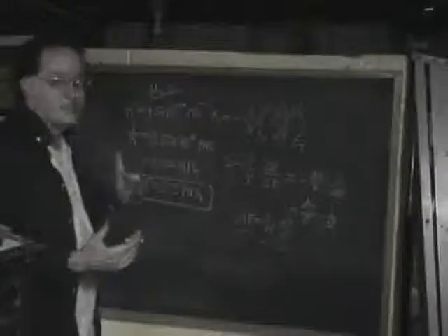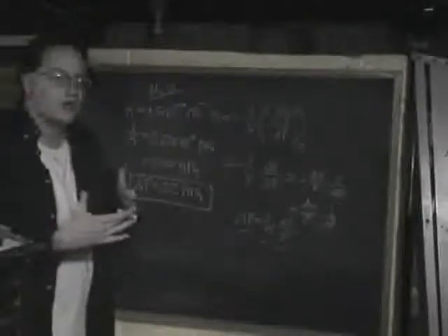So we're going to get a significant jump in pressure as this wave moves through the pipe. And this really is where the hydraulic ram gets its utility. It's from this big jump in pressure when you slam the valve closed, because water is relatively incompressible. It takes a large jump in pressure in order to affect the relatively small change in density that's needed to compress the water.